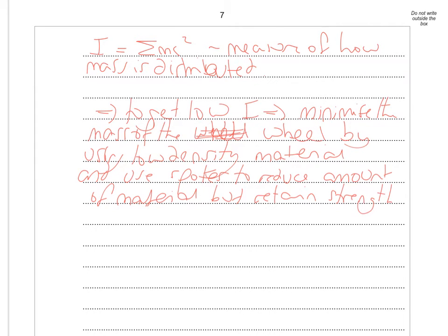The first part was explaining why a low moment of inertia is required, because for the same torque you can achieve a higher angular acceleration, so you can therefore achieve top speed faster. You could also look at it as minimising the amount of work it takes to accelerate, in terms of angular kinetic energy. And then it's explaining how the small moment of inertia is achieved. You can't really distribute the mass closer to the centre of the wheel because you still want a wheel.